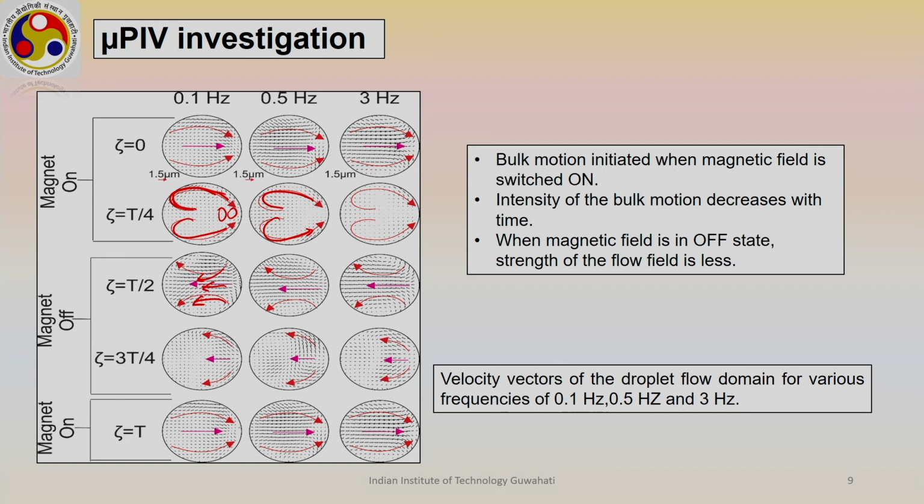And what I would like to emphasize over here is that the particles, when they are getting dispersed, are not following a random path, they are following a certain path, which is in tune with the magnetic force lines. And we can see initially we will have flow direction like this. So since the magnetic particles are following a certain path, the flow field will have a certain structure, and that is what we can see from these three